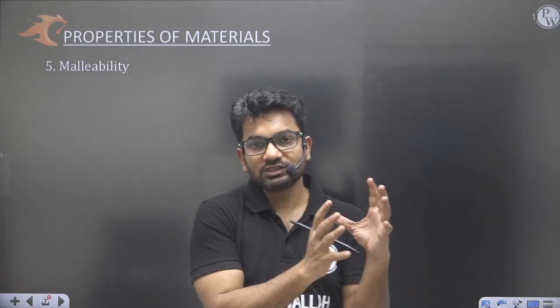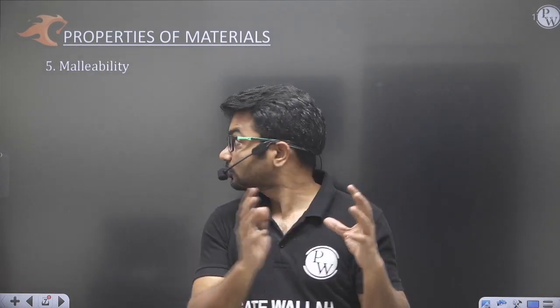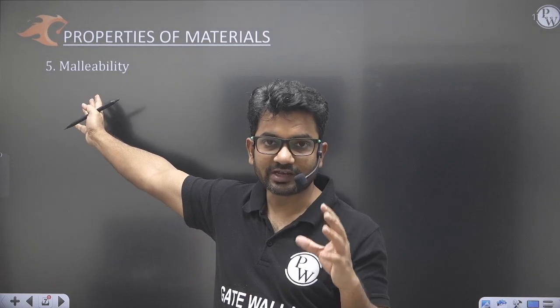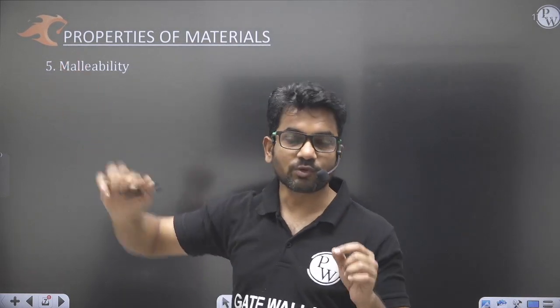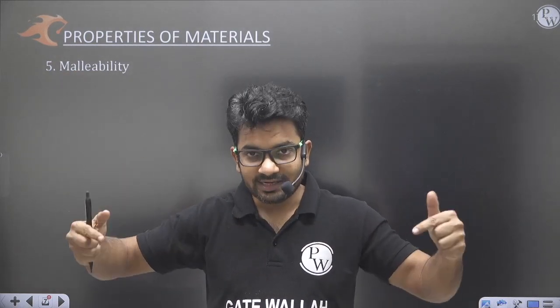called ductility. So what was the property? The property is called malleability. Sorry, I think I said ductility. That property is called malleability. So ductility was the property of large plastic strain in tensile loading. Malleability is the property of large plastic strain in compression.